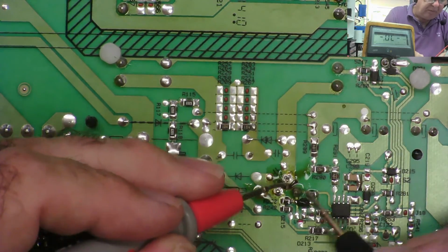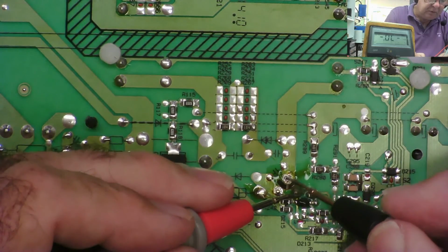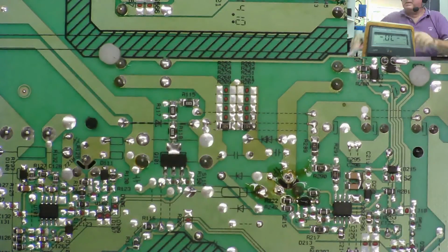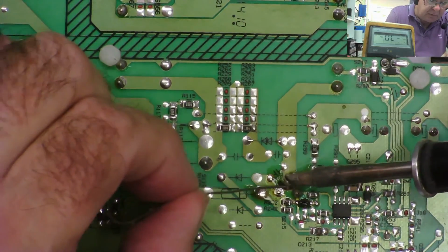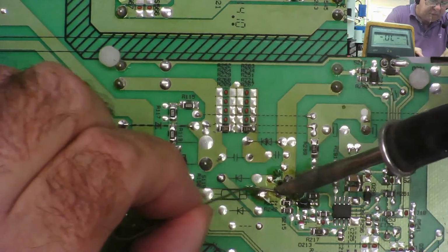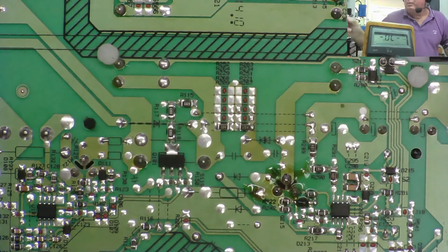As before, you might have measured the diode or resistors. Yeah? So that's a neat little trick, easily done with power transistors, if you want to be sure, yeah? And power transistors are the most likely ones to fail, so whatever's doing the most work is the most likely thing to give it up, yeah?